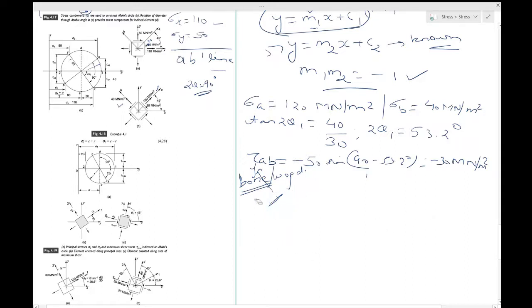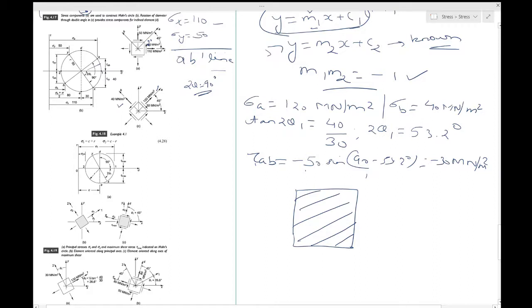And it doesn't actually end there. If this is your human bone, you can always look at it and find the fiber direction, and it is strongest in this direction. So let me find the values of stress it can take in this direction, but it will also be weakest in the other direction, which is this one. Many a time this analysis is needed to find along which direction you get the maximum and the minimum value,